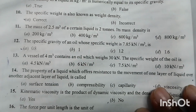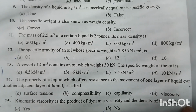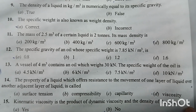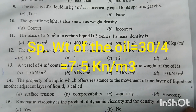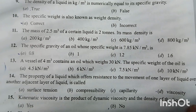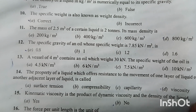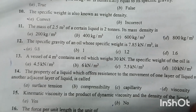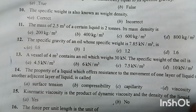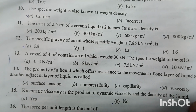Question number 13. A vessel of 4 m3 contains an oil which weighs 30 kN. The specific weight of the oil is. We know the formula for specific weight or weight density is equal to weight of a liquid divided by volume of a liquid. So here the given weight of the liquid is 30 kN and the volume of the liquid is 4 m3. So if we calculate, the specific weight will be equal to 30 divided by 4. That means 7.5 kN per meter cube. Option C is right answer.